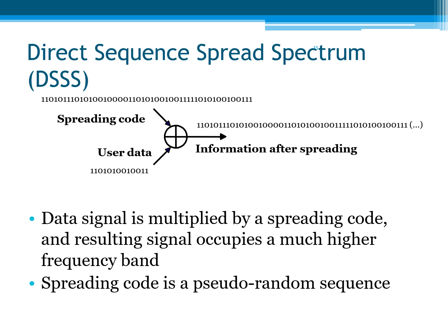Then the spread spectrum signal m(t) is transmitted through the channel, where additive noise will be added to the signal. Next, the received signal at the receiver end will consist of the transmitted signal m(t) as well as the additive noise signal. That received signal is passed to the demodulator, which consists of a multiplier and a low pass filter, where the low pass filter is used to reduce the additive noise in the signal. At the output, we get the message signal back. So this is how direct sequence spread spectrum works.